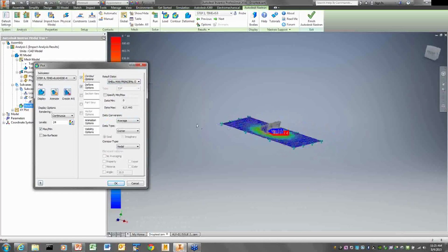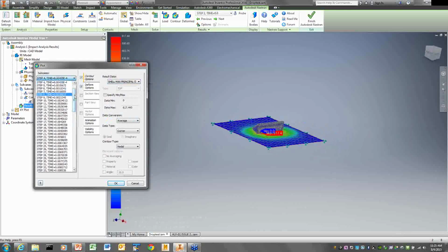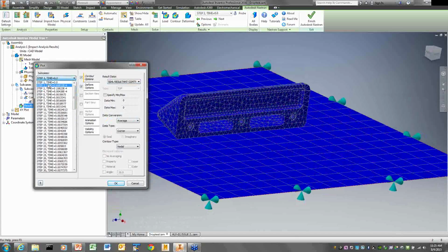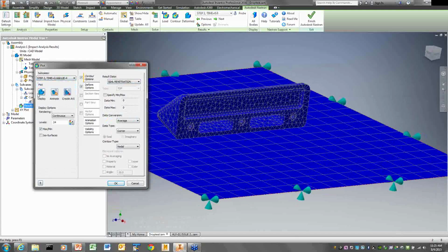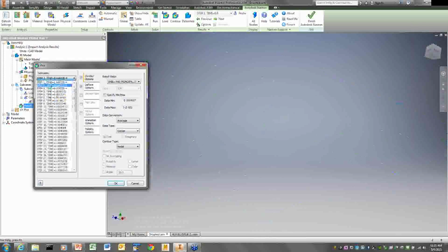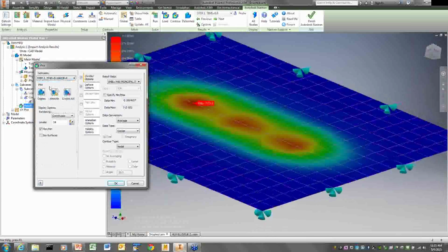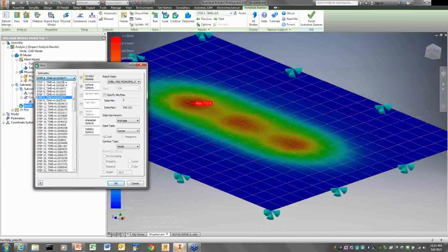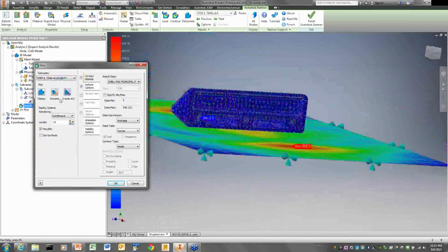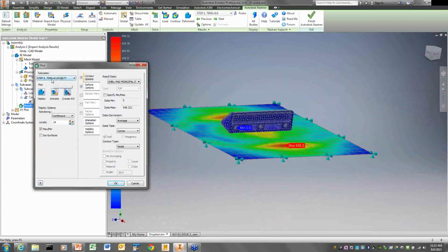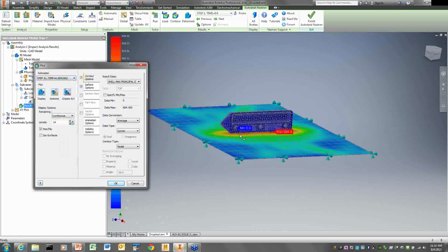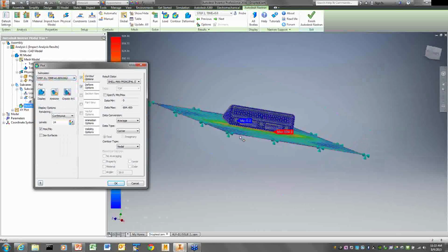Back here again, on the very first time step the shell is 0, as you'd expect. But as soon as it actually does anything, it's hit. By the time we get to the third time step, you can start to see where it's really hit and really starting to impact. As you progress through time, it hits, and by now it's rebounded. At this point it's rebounding off, and this is only time step 8. So you can watch a progression of stress waves moving in and out and flying away.